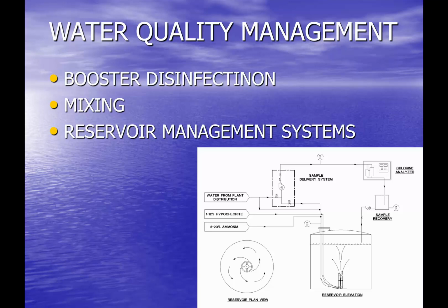The system will then continue to monitor the water that's in the reservoir to assess what the residual is, and to the extent that you need more disinfectant, more chloramines in order to achieve that disinfection residual, then it'll start adding more. So it's an automatic control system that looks at the residuals you've got, and then will increase or decrease the amount of chemical being added in order to maintain a more consistent residual in that reservoir.